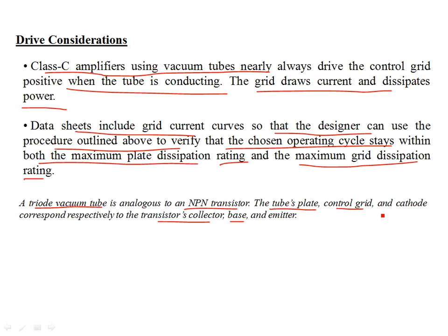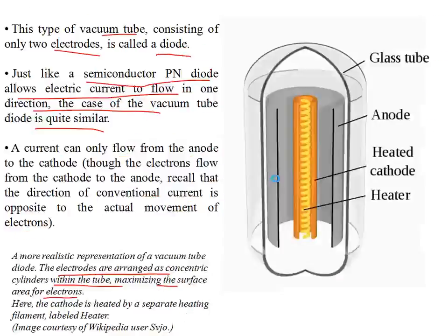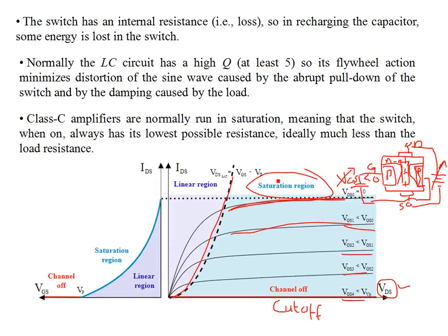The cathode is the emitter, which emits electrons while it is heated by thermionic emission, and the electrons flow towards the anode in the vacuum, or evacuated, envelope. The operation and characteristics are very similar to BJTs. But if you are going to use a vacuum tube, you consider these IV characteristics, the plate current and the plate voltage, instead of JFET saturation regions.